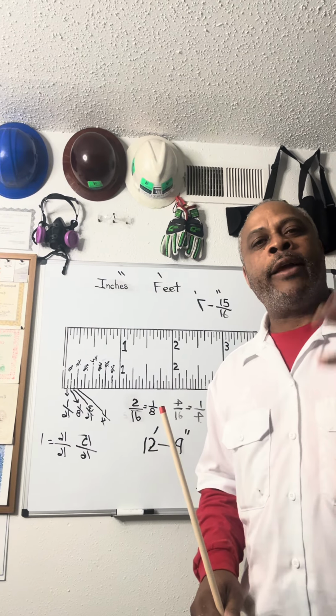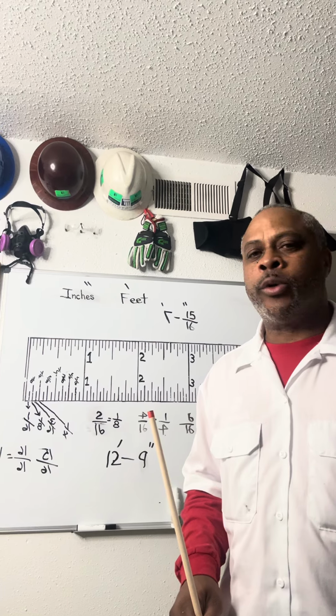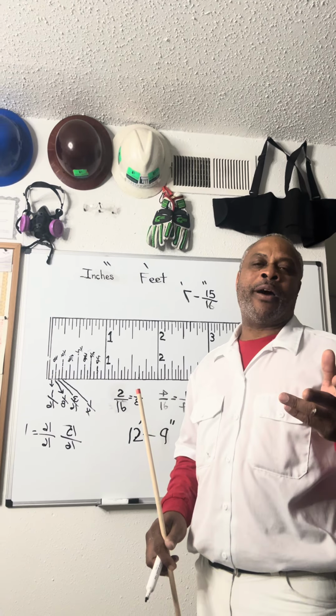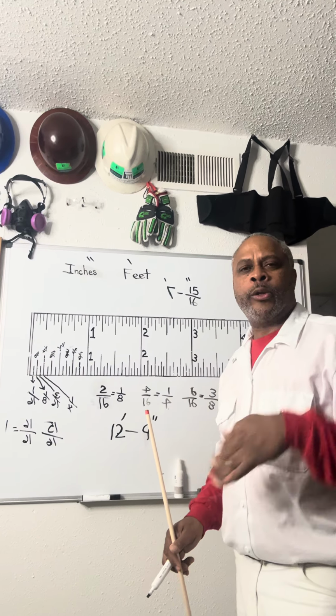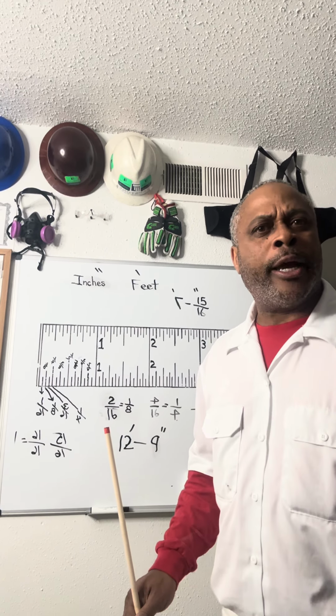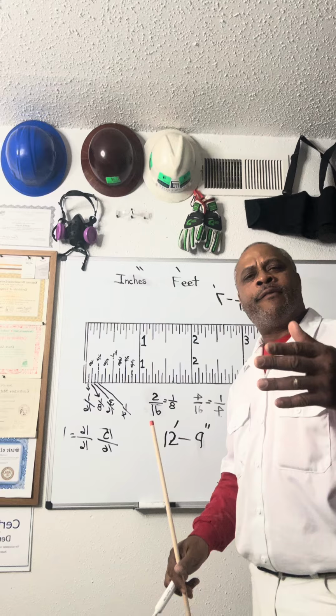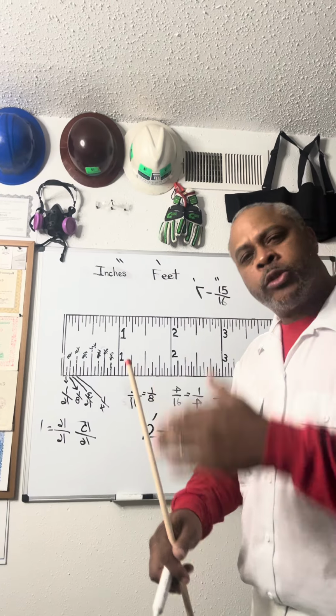But studs are cut at a certain length when it comes to certain walls. An 8-foot wall, California, 92 1/4. You go to the South, 92 5/8. Why? I was like, okay. But that's just the way it is to get 8-foot. Now things like 104 1/4 studs or 104 5/8, that's for a 9-foot wall. So you got to know stud height.